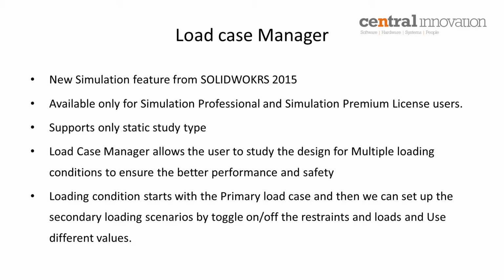And what is the purpose of using Load Case Manager? What it can do? By using Load Case Manager, we can set up different multiple loading conditions, and it has an interface, something like a table. So once you set up all your fixtures and your loads inside your simulation study, these details will be transferred onto those tables.